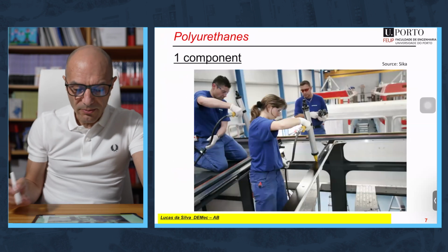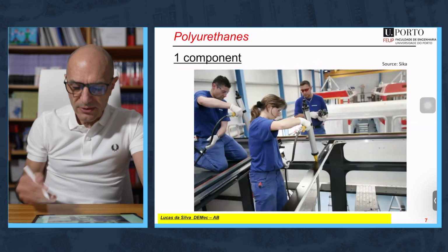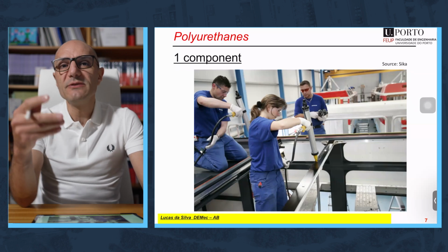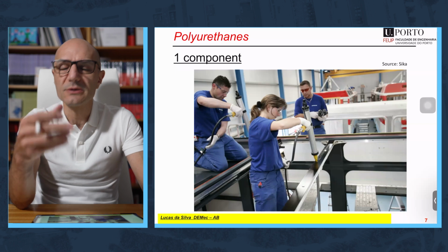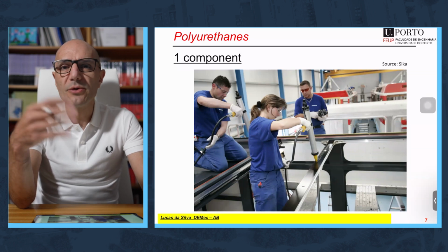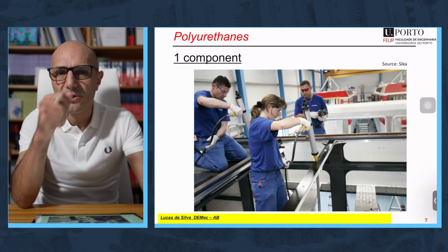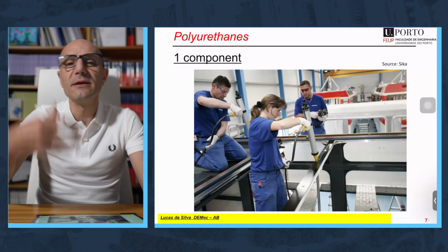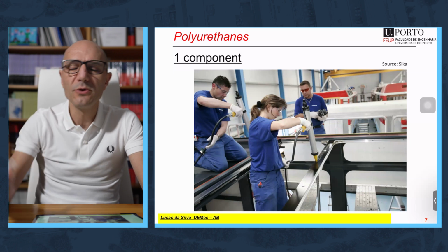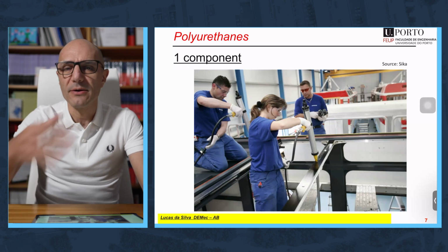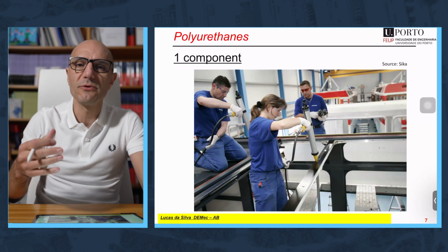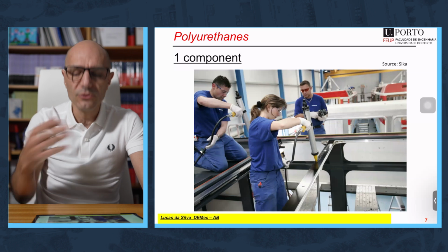Typical applications. One component, as I told you, the windscreens or the panels, the side panels in the buses. This adhesive cures by absorption of water, so it takes really long time to be fully cured. Typically 2-3 weeks to be fully cured up to the core. Of course, you can handle the joint after a few hours. That's what happens when you go to repair the windscreen of your car. But to be fully cured, because the absorption of water is very slow, it would take typically 2 or 3